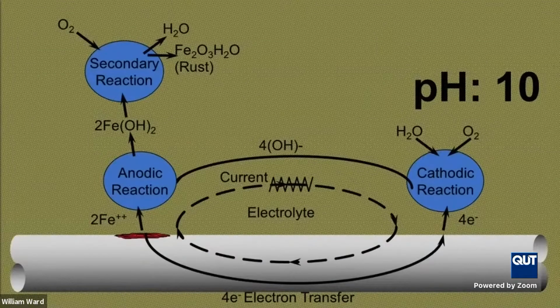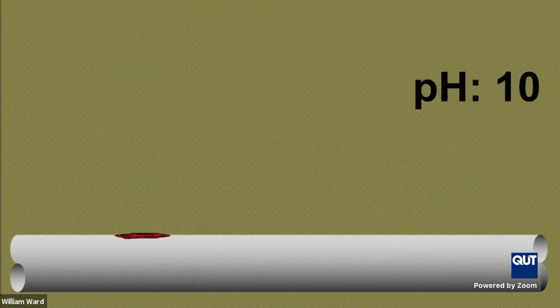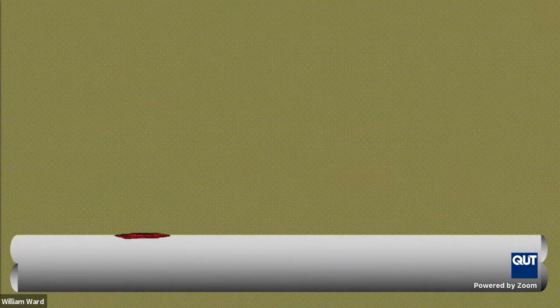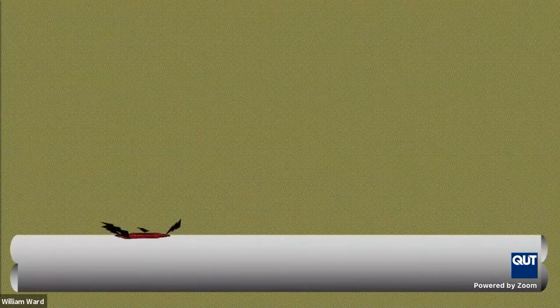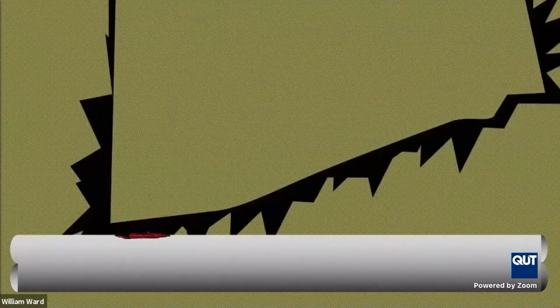Rust or corrosion product will form. And then we're going to start to get the physical results of this corrosion activity. We're going to begin with cracking and eventually damage, spalling, and breakdown of the concrete. So that's the life cycle of corrosion in concrete for this particular mechanism.